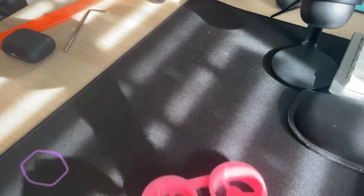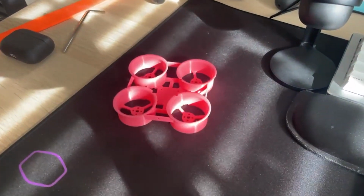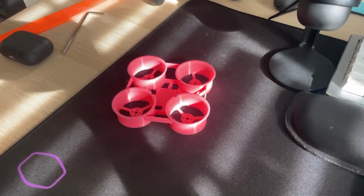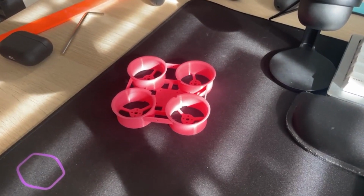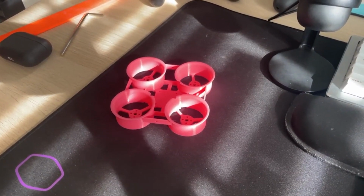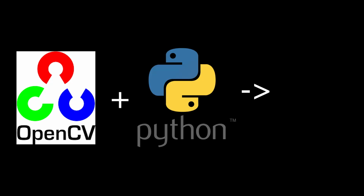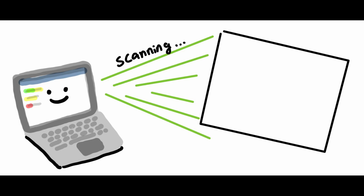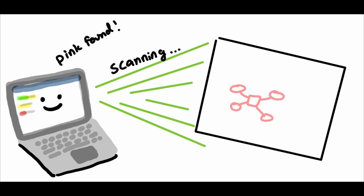This is a test chassis that I found on Thingiverse and printed on my Ender 3 printer, as my teammates are currently working on the actual chassis. But if you haven't noticed already, the chassis is pink, which is actually by design. Using OpenCV in Python, we can detect the drone by looking for the color pink, since we found that in most settings this color is uncommon. We scan the entire screen pixel by pixel and look for the color pink. The program then will choose the largest blob of pink and select that as the drone.